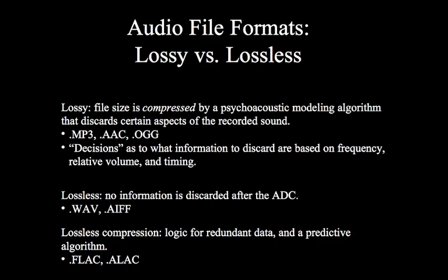Now remember, all digital audio is lossy, right? Because no matter how fast we sample, there's always going to be a space in time and a space in amplitude in between those two different measurements. It's never going to be continuous. However, when we talk about lossless in terms of digital audio, we mean whatever the analog to digital converter measures, that's what gets written to disk.